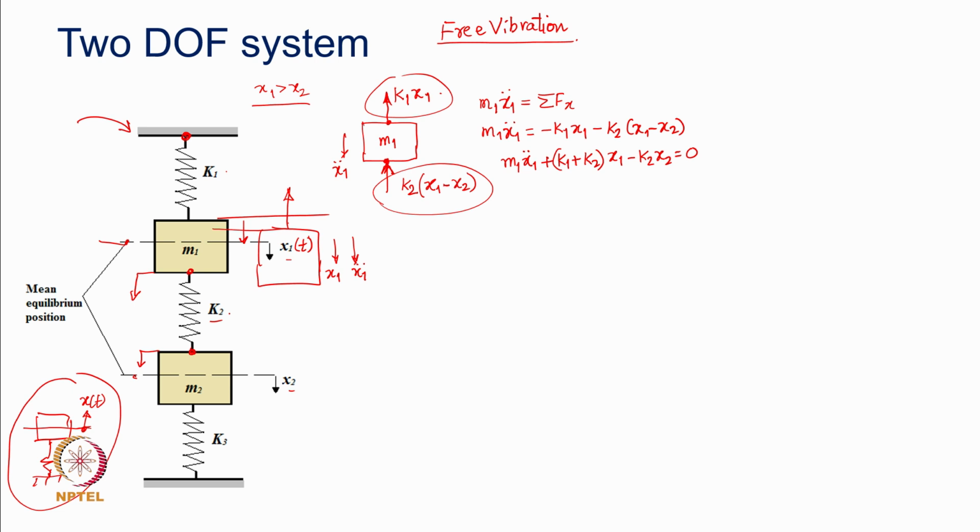Okay. Now, we have got the first equation for sure. Let us get it for the second mass now, the way we did it for the first mass. The second mass m2 will have similar acceleration downwards, and when it tries to go down with the displacement x2, this particular spring gets compressed because its other end is fixed and this end is being pushed down.